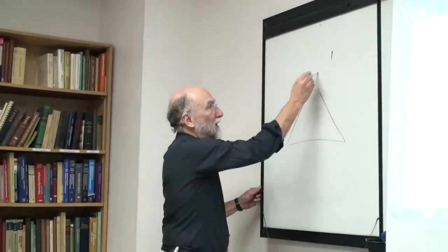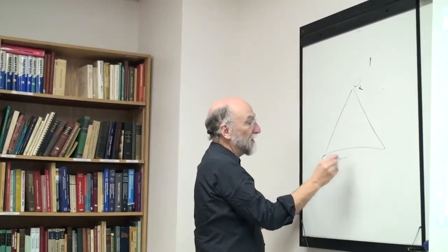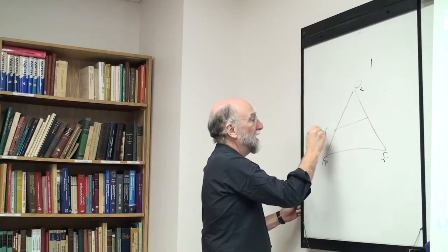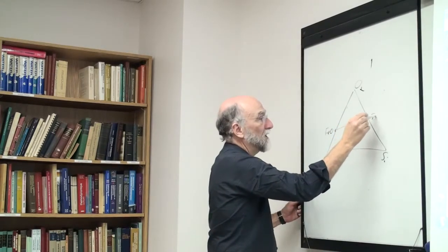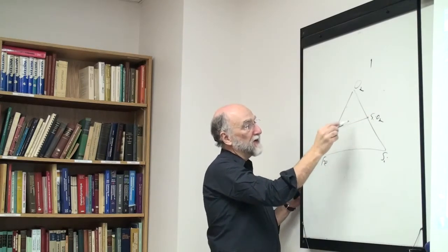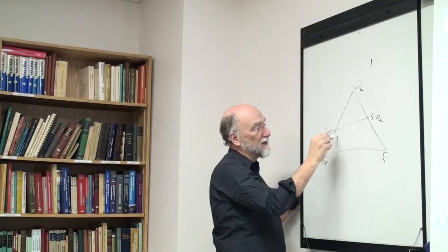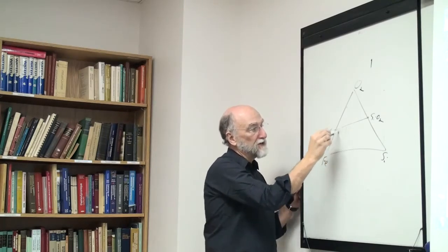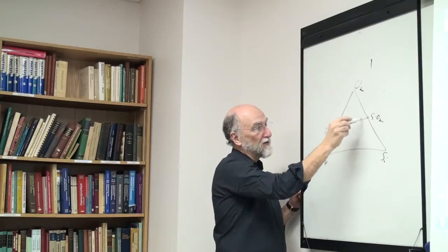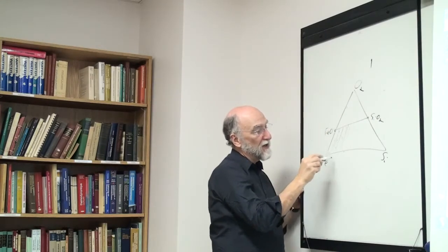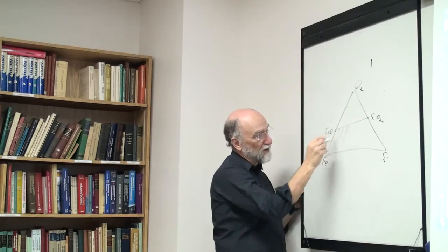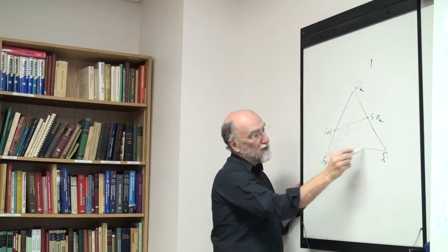So the way I like to think of this diagram, or the way I calculate this diagram with FactSage, is I consider it to be an isopleth, FeO SiO2. What you're going to have is oxide phases which lie pretty well on that line in equilibrium with the metallic phase down here. You can be in a two-phase region between phases that exist on the oxide phases, and then you can have a metallic phase. In the iron silicon system, the metallic phase is basically all pure iron.